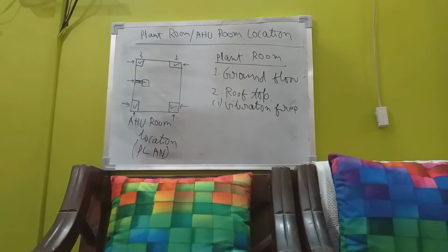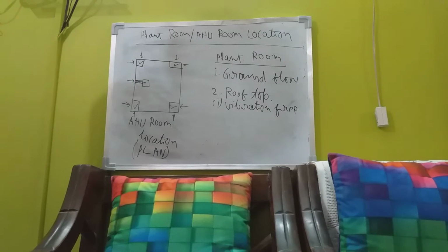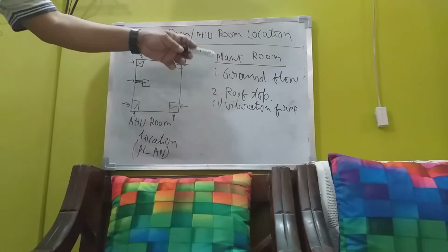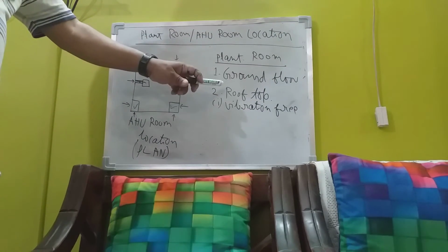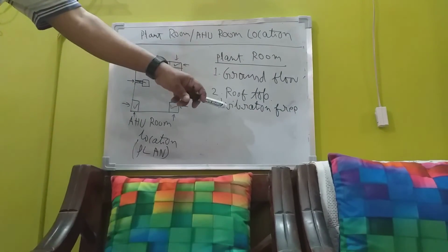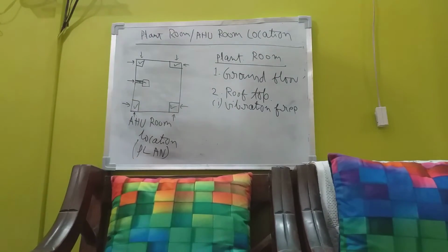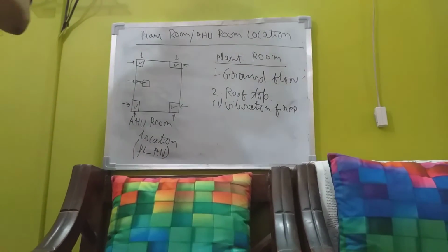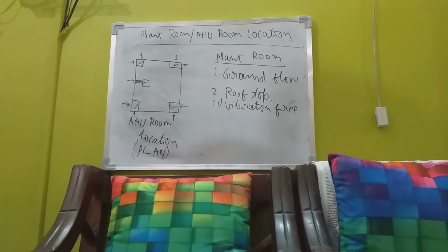Because chilling machines have a terrific weight, the roof should be properly designed. After it is properly designed, you can place the chilling machine at the rooftop, but the architect should instruct that the roof be made capable enough to take the chilling machine, and should give this direction to the civil engineer who is constructing the roof.